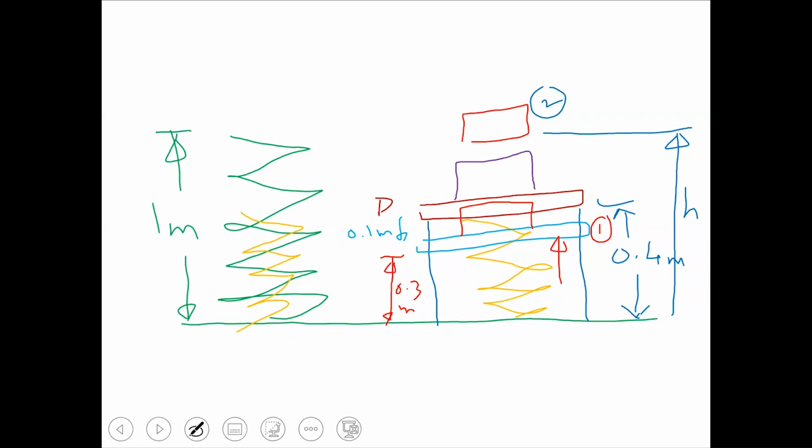No sir. Okay, so coming towards the solution of this problem. Okay, applying the principle of work and energy here, T1 plus summation U1 to 2 should be equal to T2, that is the initial kinetic energy of the block. We are applying the principle of work and energy on the block. So the initial kinetic energy of the block plus work done by all the forces on the block should be equal to the final kinetic energy of the block.